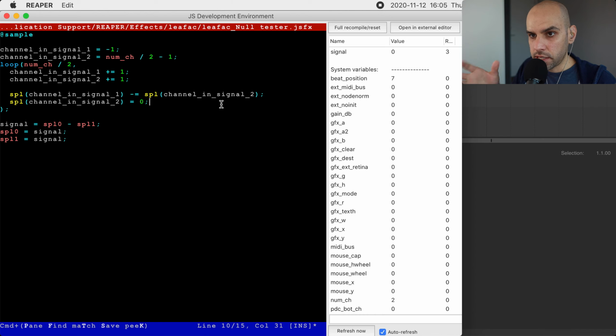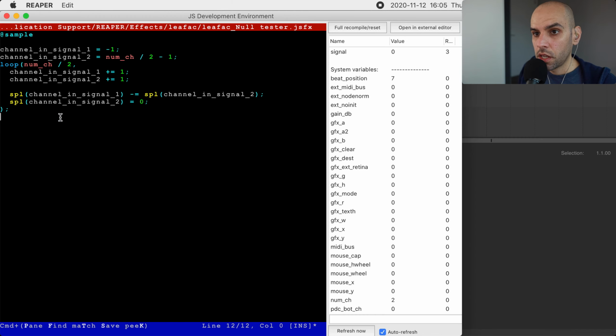there. And this is going to slightly change what we saw in our previous example, because previously we were outputting the signal to both channels, but now we are not. We are only outputting to the left. And in this case, if you have mono signals and you have 2 of them, like we have here, one on the left, one on the right, then you will hear their difference only on the left, because you only have number of channels divided by 2 outputs.